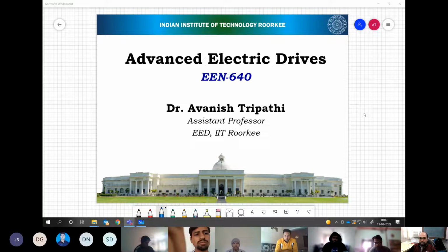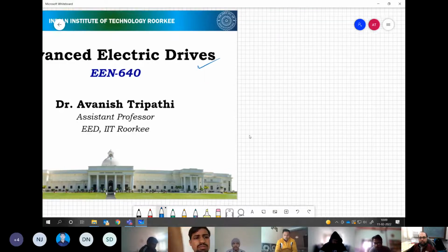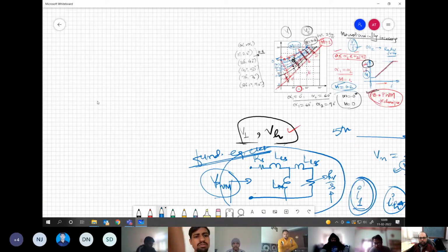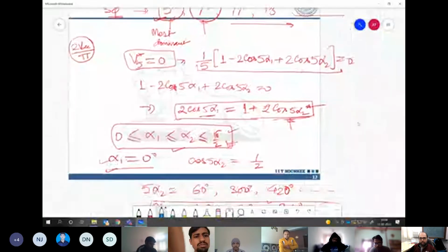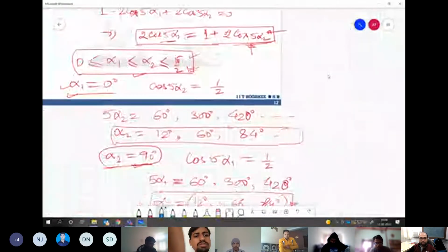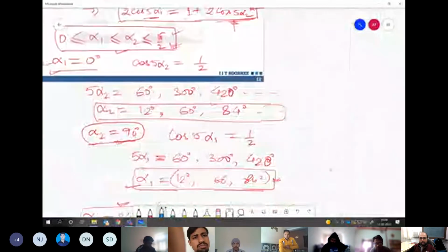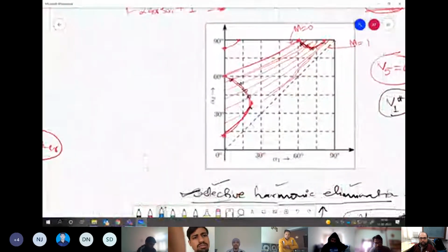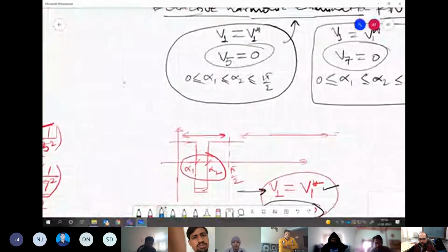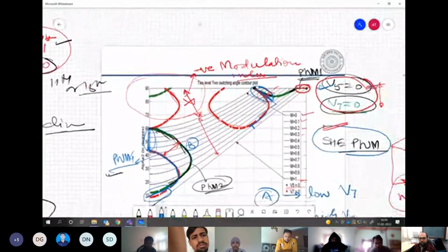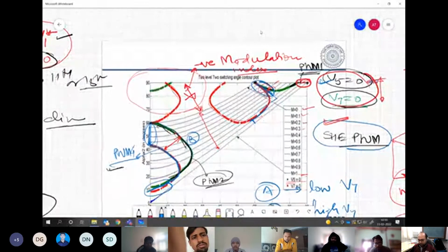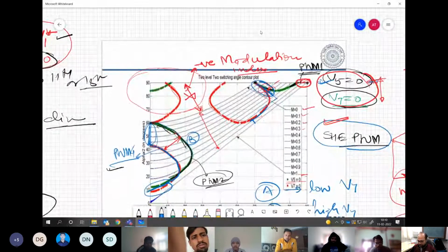So we have the 19th lecture today for this course, Advanced Electric Drives, and we have seen the different PWMs so far, which are selective harmonic elimination and then optimized pulse width modulation. What are those and what are we trying to achieve? We saw that when we have enough degrees of freedom, we can eliminate the dominant harmonics. Let's say we have two switching angles per quarter, which means 2 degrees of freedom.